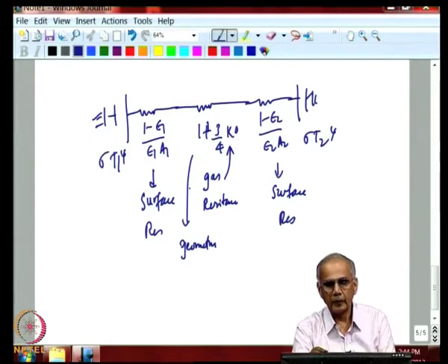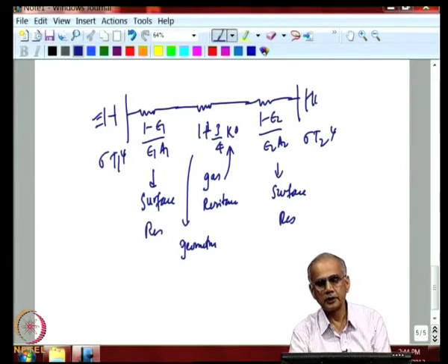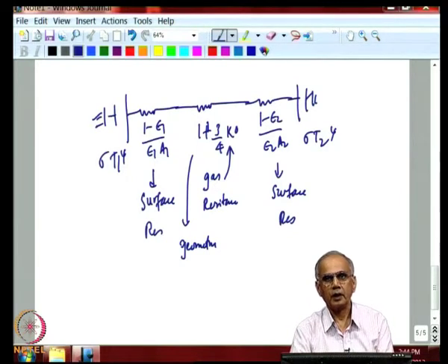So, this kind of electrical knowledge is useful to understand which particular mechanism offers maximum resistance to heat transfer, and that should be the one we should be focusing on. The others are not that important.